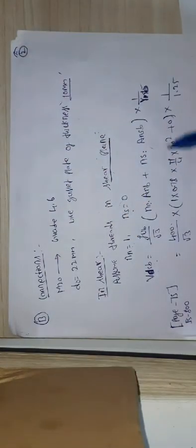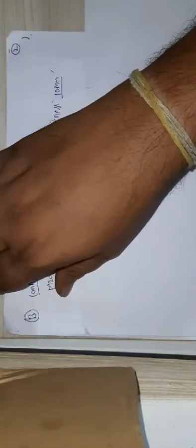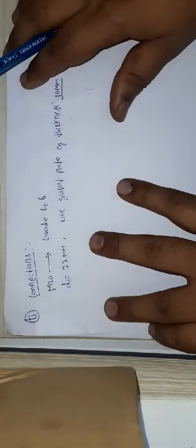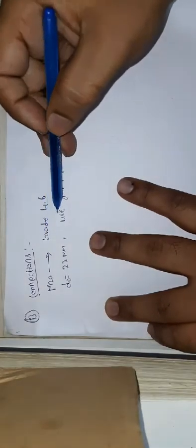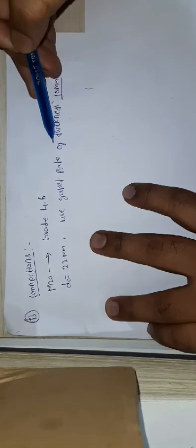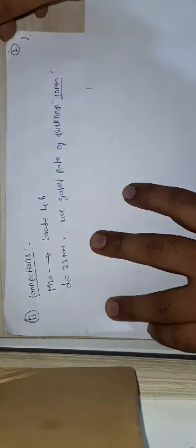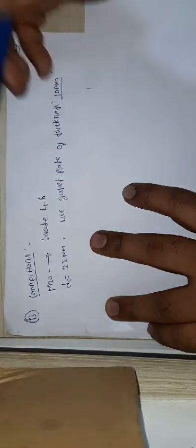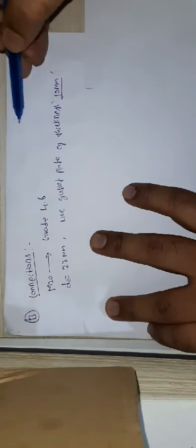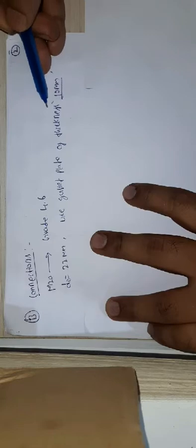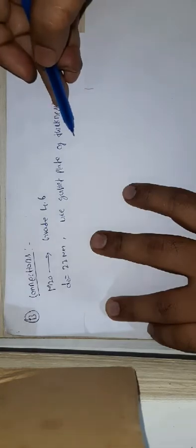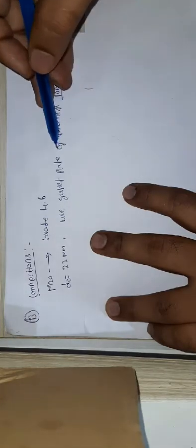Your next step is to find out the number of bolts required for the connection. So the next step is to calculate the connections, or find out the number of bolts required. For that I need to calculate the strength. I need to calculate the shear strength of the bolt and the bearing strength of the bolt. By using that, I select the bolt value. Then I can calculate the number of bolts required.